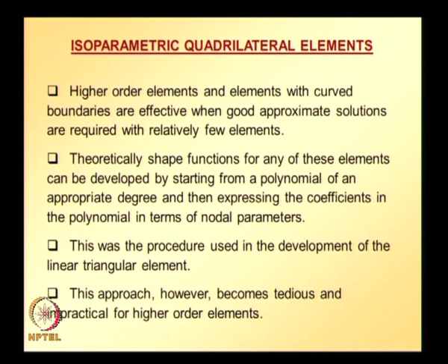shape functions for 1D elements and also the linear triangular element, but that approach becomes tedious or impractical for higher order elements. That is, as the number of nodes for a particular element increases, we need to choose a polynomial having as many coefficients as the number of nodes for that element. So, solving for these coefficients, substituting back, and grouping terms having common nodal parameters becomes tedious for higher order elements.